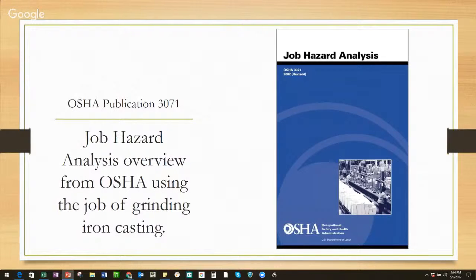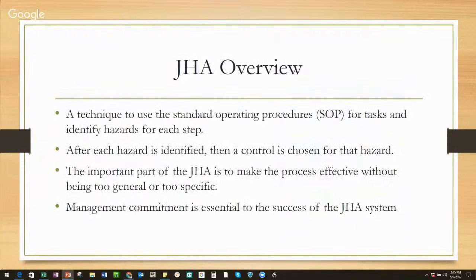There's so many different, like I began to tell you in the beginning, a lot of people have developed different types of job safety analysis. So one of the things that you will see is this is a generic basic type one, but your company may actually have something even better, more specific. So there's one, a JSA on the grinding. It's a little step more, or actually it's a lot step more than your standard operating procedure, because your standard operating procedure is just telling you how to do the job. That's it. So where the JSA takes over is now it's telling you how to do this job safely as it's itemized per line, per step on the job.